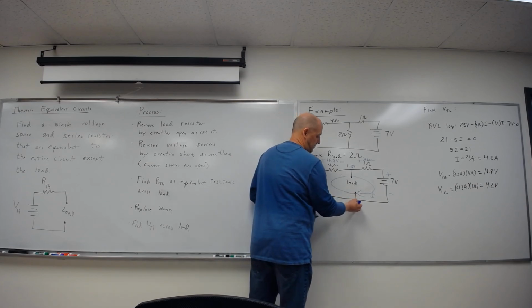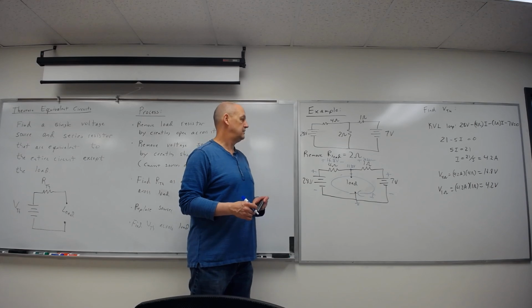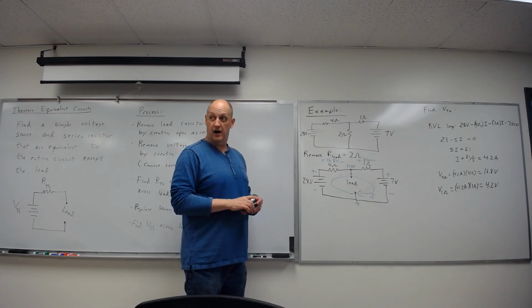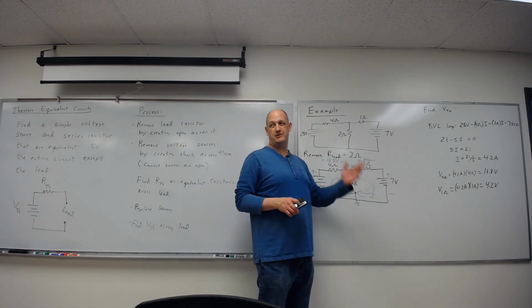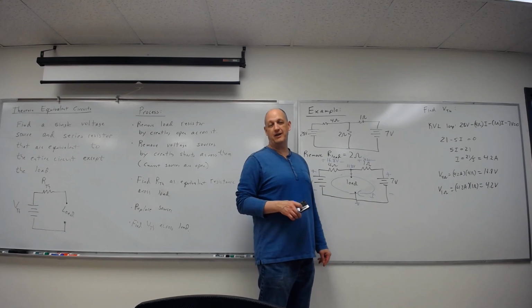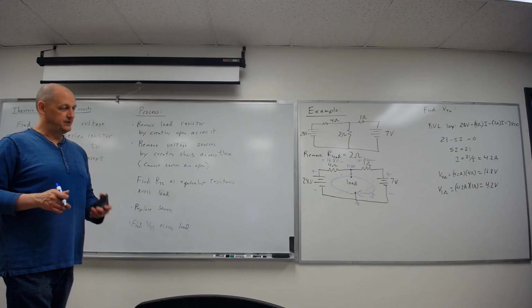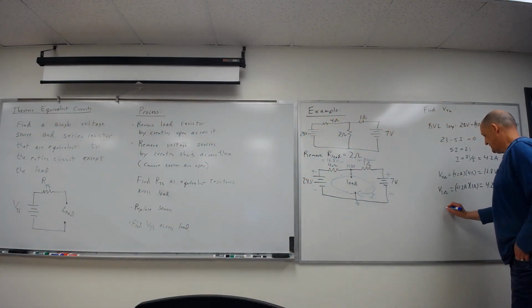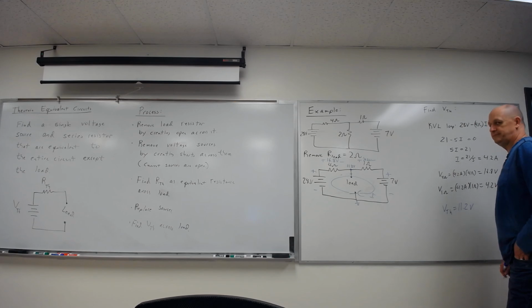That's relative to here. I can also see the other direction. If I just look here, I got in 7, 4.2 would be 11.2 volts, right? Either way, I end up at 11.2 volts. And that voltage is what I want. So I'm all done. This Thevenin voltage, I started right at T. It's 11.2 volts.